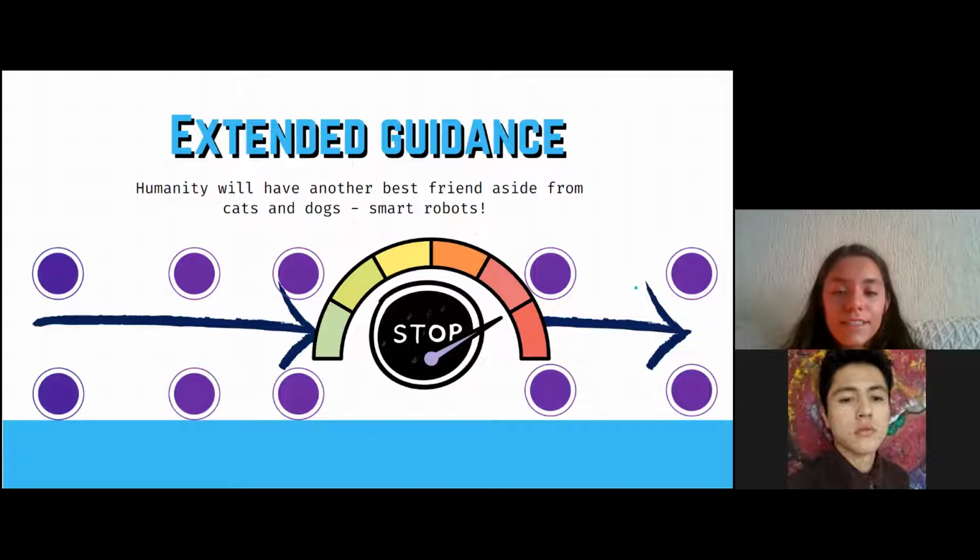And we have the extended guidance. This allows you to specify, together with the points through which the robot must pass, data relating to speed, types of trajectory, precision with which you want the points to be reached, program flow control, attention to binary inputs and outputs, etc. In this case, the guidance method used is that of the joysticks. Extended guidance programming greatly increases the power of the programming system.